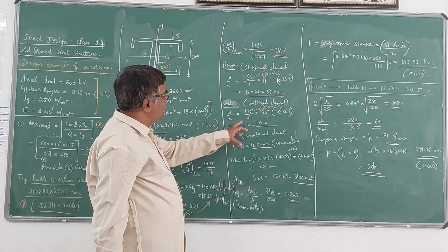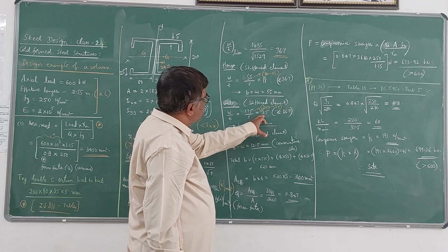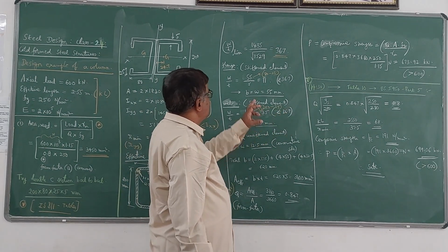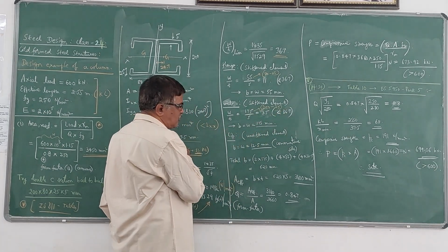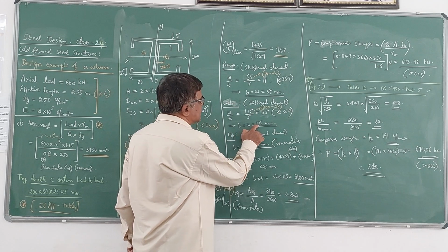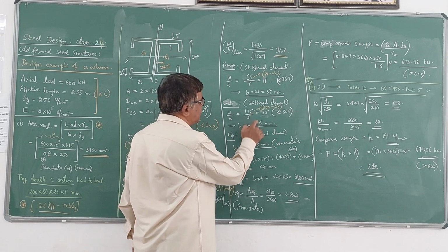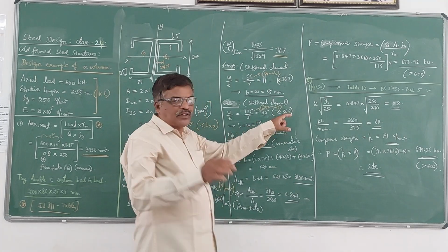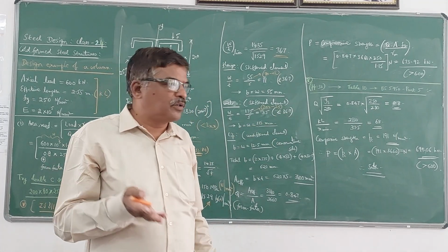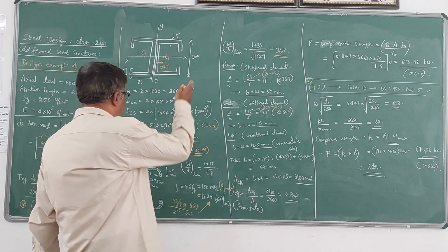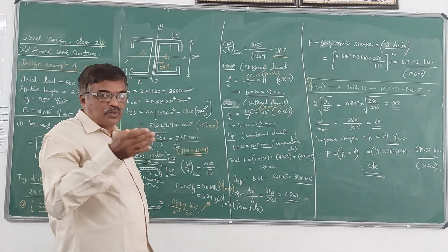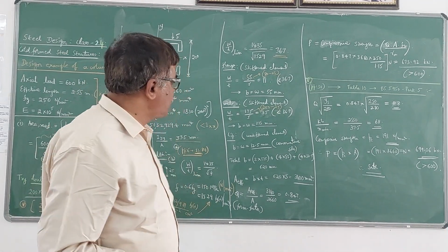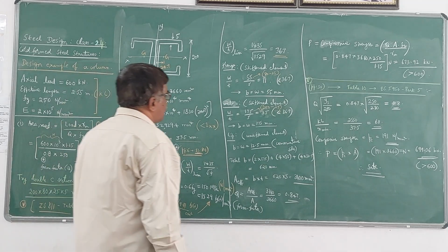If you calculate this you are going to get 35. This is also less than 36.7. Then the value of B is taken as equal to W, which is 175 here. Suppose if you get this value greater than this, then there is a formula to find out that B in the same page number 6, which I have used in the last problem, last lecture.